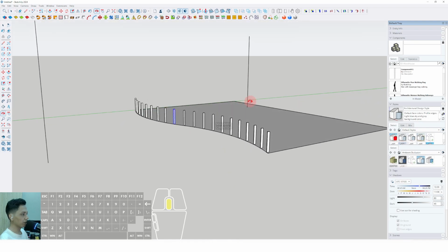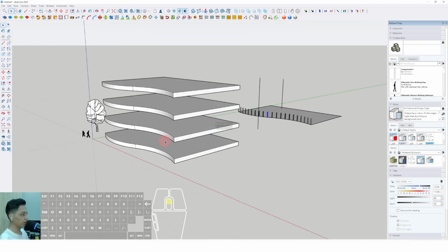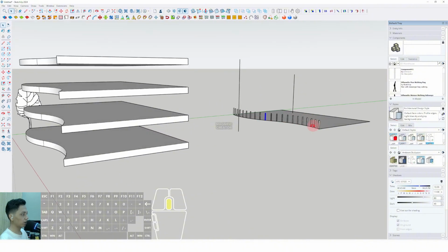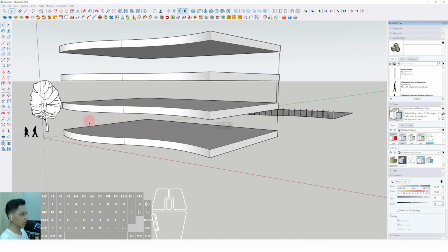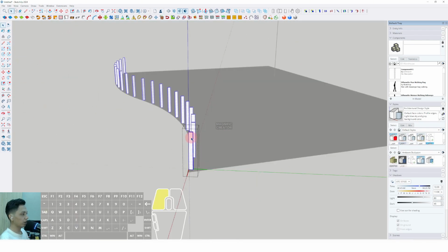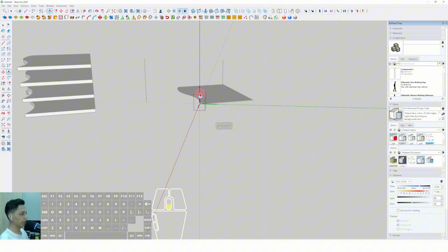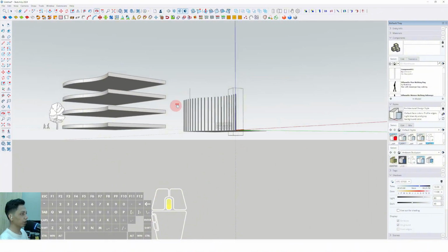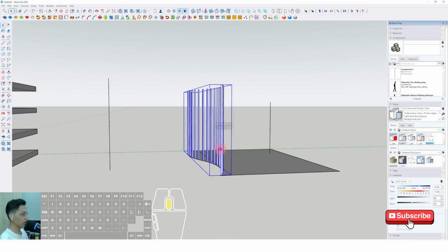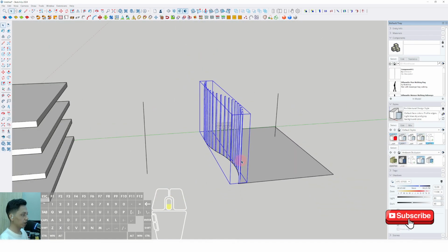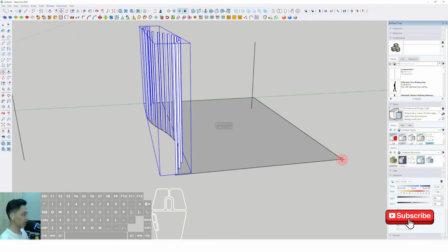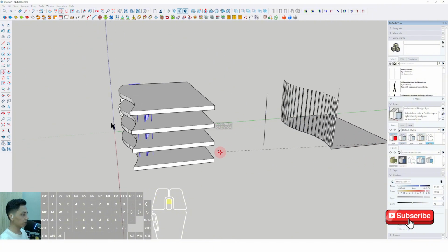of the commercial building. Okay, then we have to duplicate, then we have to extend or place to this appropriate position in it. Okay, then we can push it up until this position. Okay, then we can select it all and right click and make group, and okay, we can select move, press Ctrl and place from this endpoint until this endpoint.